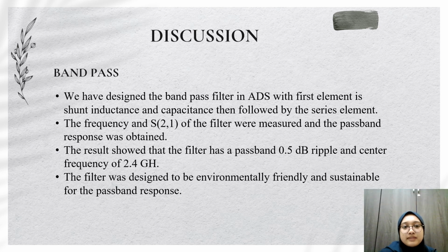As for the bandpass filter, we have designed it in ADS with the first element being shunt inductance and capacitance, followed by the series element. And then the result shows the frequency and S21 of the filter were measured and the passband response was obtained. And the results show that the filter has a passband with 0.5 dB ripple and a center frequency of 2.4 GHz. And the filter was designed to be environmentally friendly and sustainable for the passband response.